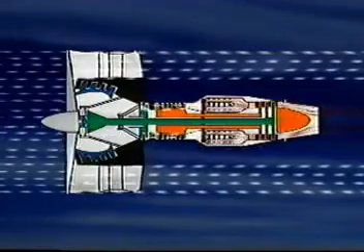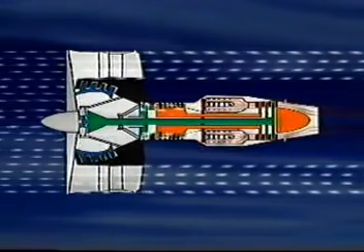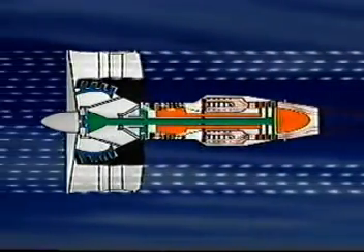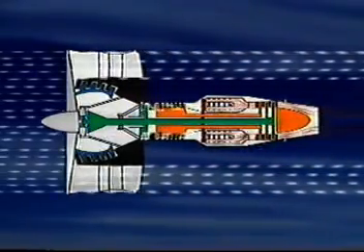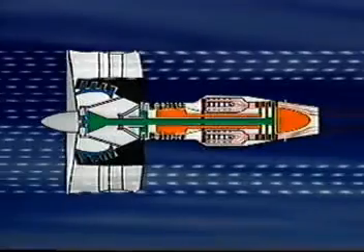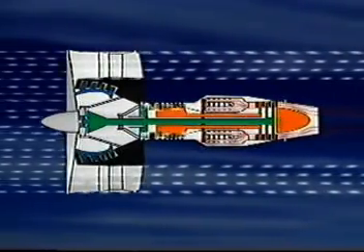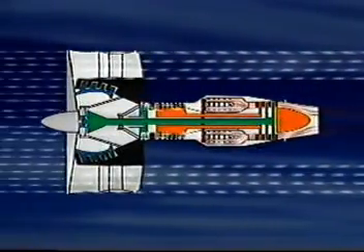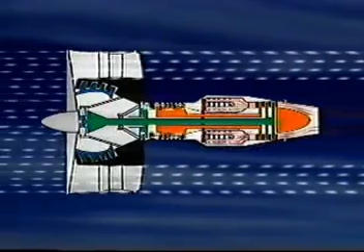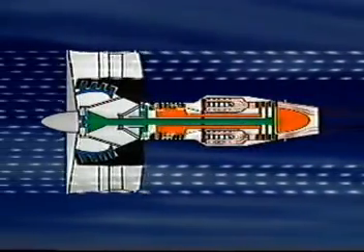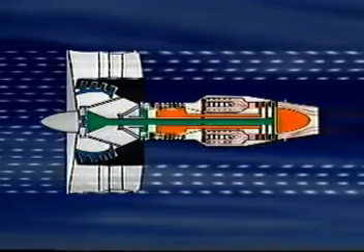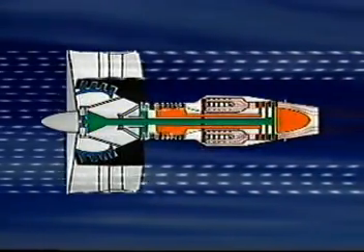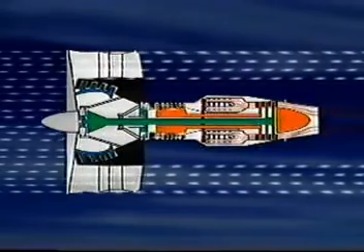The turbofan engine is much like a turboprop, except that the propeller is replaced by a fan with rotating blades and stationary vanes, actually a compressor of large diameter. The fan is enclosed in a duct. Part of the air entering the engine intake, after being processed by the fan section, bypasses the central engine core and expands in a separate nozzle to provide cold thrust. The bypassing air is not burned with the fuel.